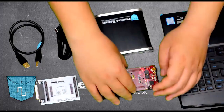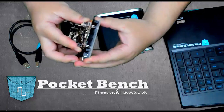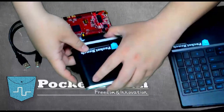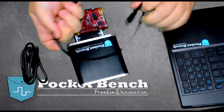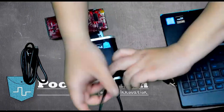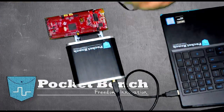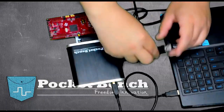Let's deploy the PocketBench real-time simulator. First, connect the DSP launchpad to the interface board. Then connect the interface board to the PocketBench. Finally, use the USB cable to connect both launchpad and PocketBench to the computer. PocketBench can simulate the power converter in real time. When the controller injects PWM stimulus to the PocketBench, it will receive the voltage and the current response in real time, just like being connected to the real power converter.